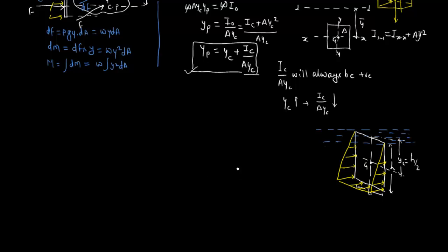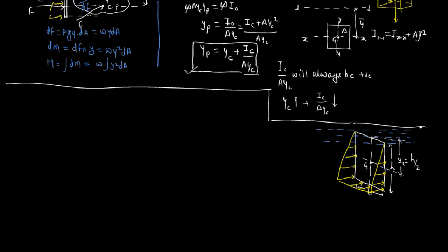So obviously the hydrostatic force in this case, I'm saying, will be F is equal to wA yc. Okay, so this force is exerted by this fluid over this surface. So here the area of the plate is b into h. Okay, now we will try to calculate the yp. So let's suppose around here is yp.